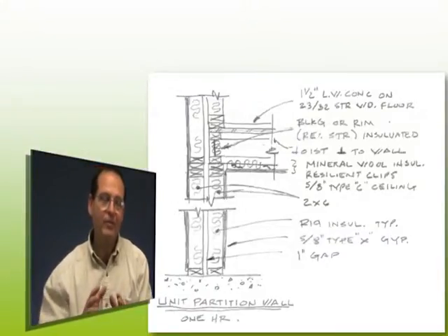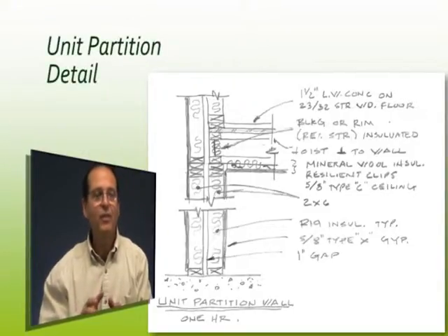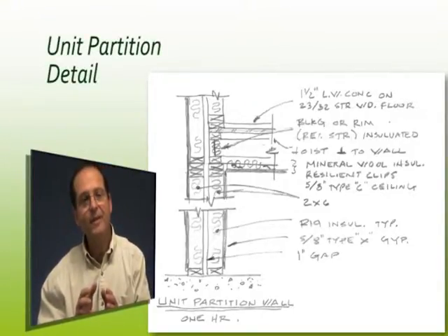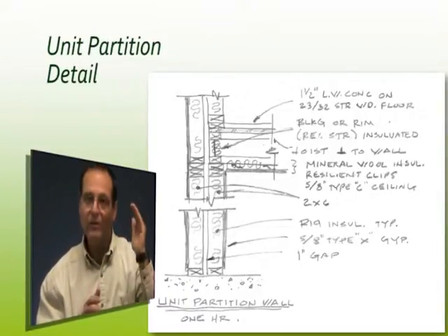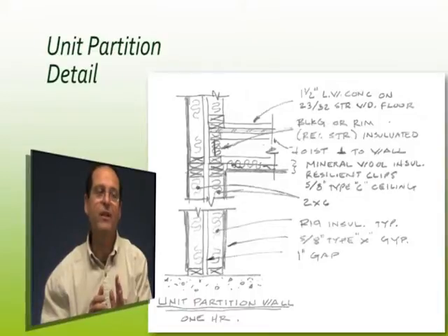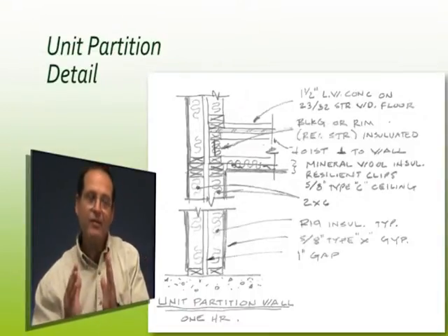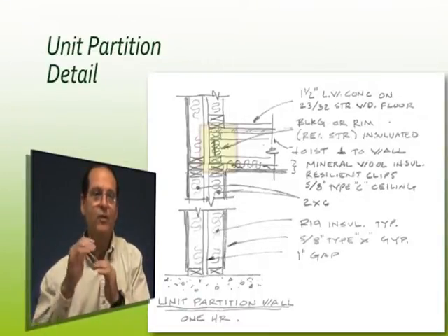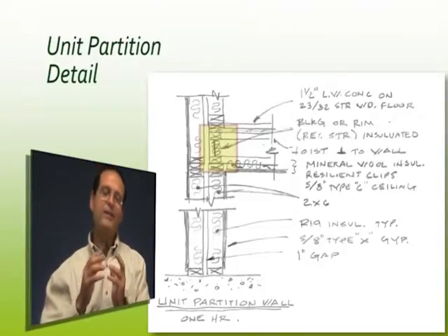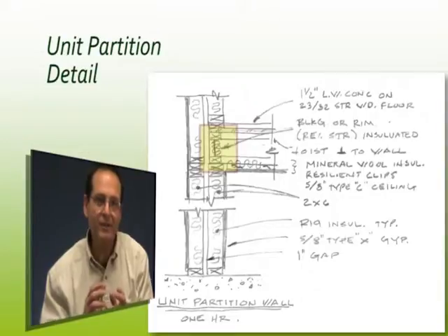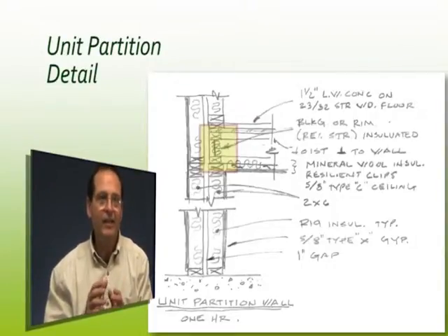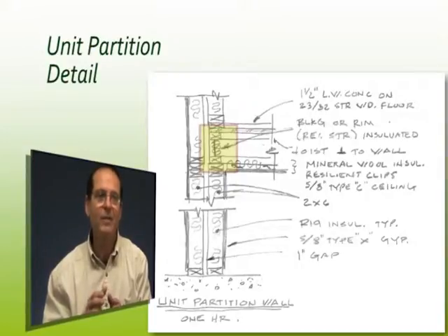The only last piece I want to show you here is the fire wall assembly again. So on the left-hand side, what you can see, this is actually a stairwell opening, so it's 2 floors high. We're just stacking walls on top of the other. No-brainer for that interior wall. The other wall that's in there, notice that the joist sits in it. So this is where things can get a little bit goofy. I mean, how you interpret this can vary. You can see the interpretation that this particular architect and building department came up with.